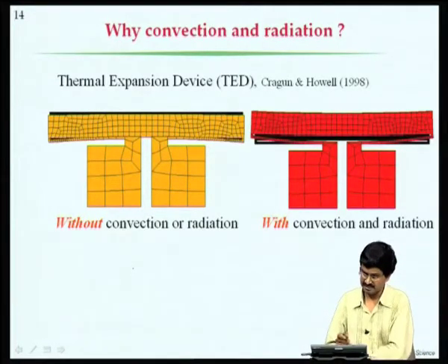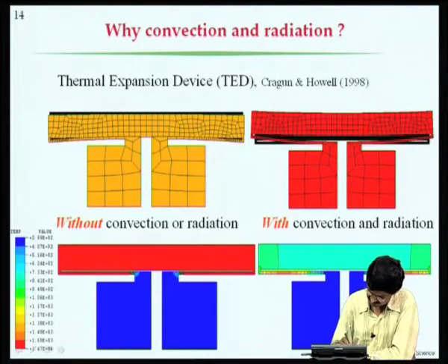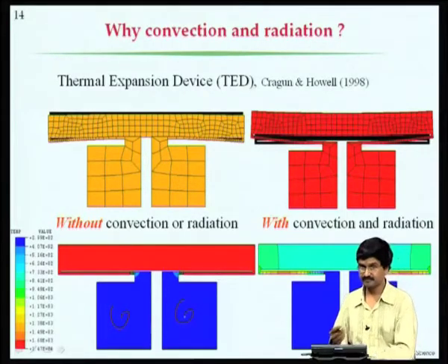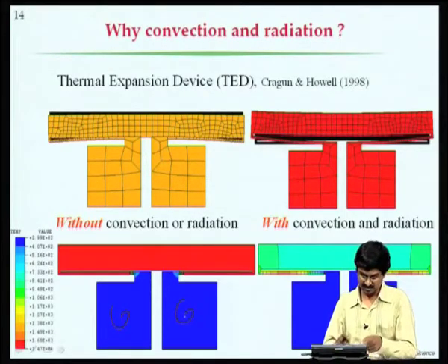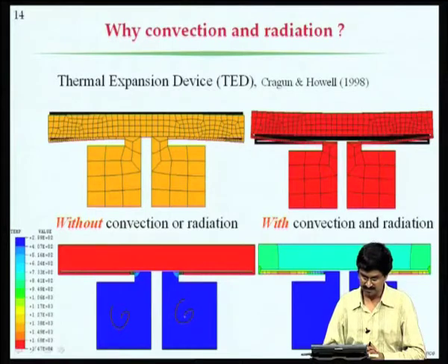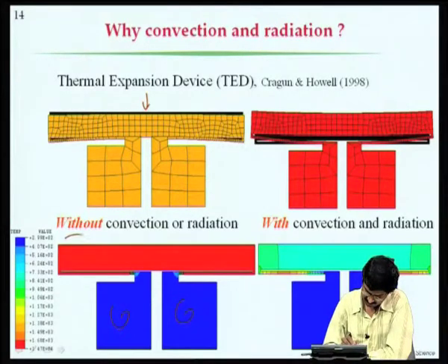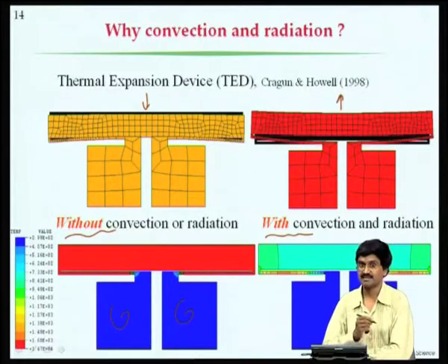Okay. So, if we take a structure, I think it is easier to see. Again we have put a slit here, that is a narrow slit, and this is the place where between these two we are applying electrical potential, non-uniform heating, and according to this it is supposed to go up, the way this would bend, it should go up, but actually it is coming down, as you can see when you model without convection. When we model with convection, it is actually going up as intended.